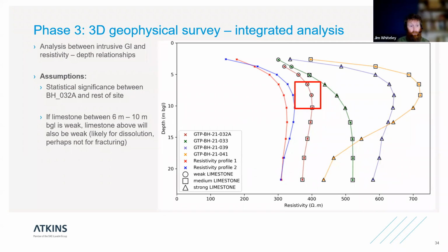Now, we have screened the data for cave formation already because if you had an air-filled cave, resistivity would present as incredibly high values, talking tens of thousands of ohm meters, and the maximum we're seeing across this model is more in the 1200 ohm meters, so a good order of magnitude less than we might expect if we had open voids in the ground.